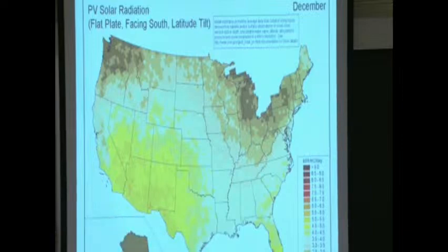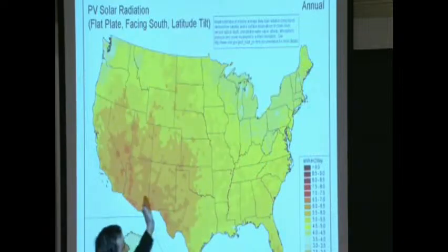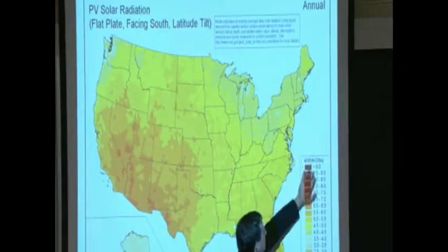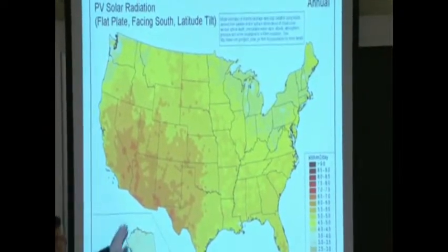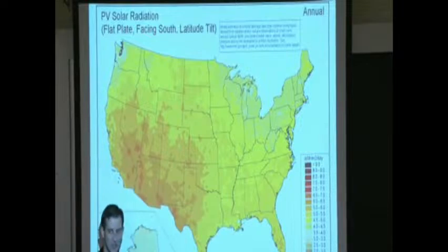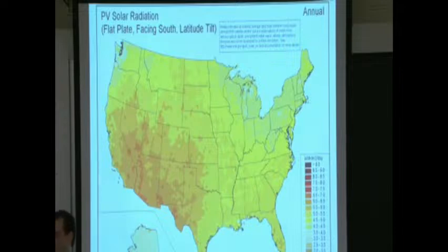So that's pretty nifty. And another nifty fact, if you look at the year average value, annual, this is the annual average value. Here in Boston, we're averaging around 4.5 kilowatt hours per meter squared per day. Phoenix, Arizona can be upwards of 6, somewhere in the outskirts. It's not that bad, it's only a few tens of percent.